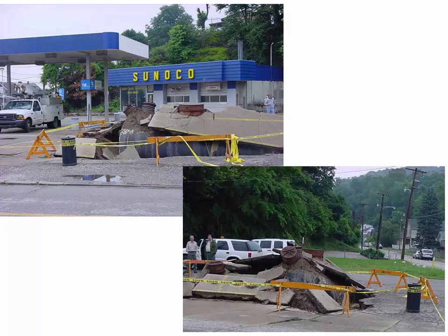But a tank that is full of gasoline is going to be pretty heavy. So it's going to have a lot of weight, and it's not going to all of a sudden crash out of the concrete. If it's really rainy and wet, this water table can rise. And so if the water table rises above the tank and it's full, we're still okay, because there are going to be some buoyant forces, F sub B, just like a boat will float in the ocean.